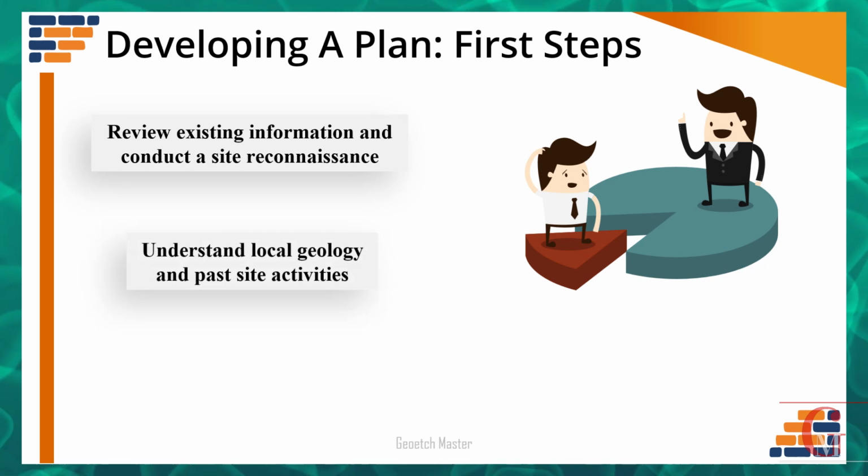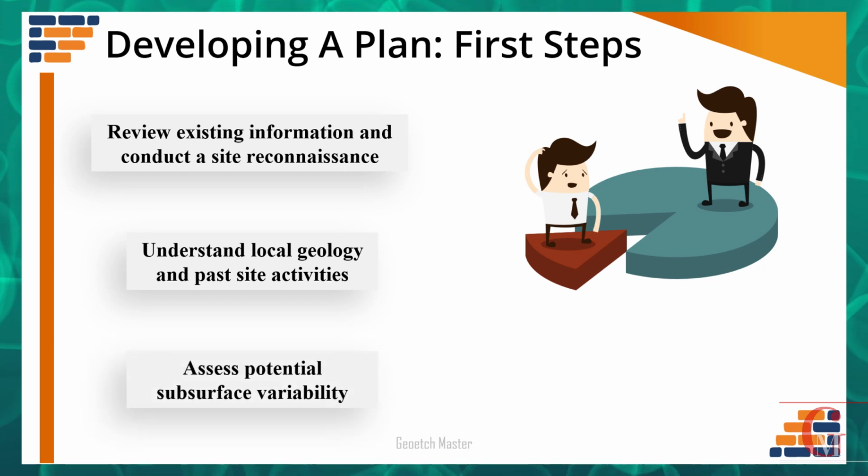This will allow you to understand the local geology, the past activities at your project site, the potential variability in subsurface conditions, and the likely performance issues you need to evaluate. Based on the site reconnaissance report, you will now understand what types of data you need for your project. You can then look at geophysical testing.